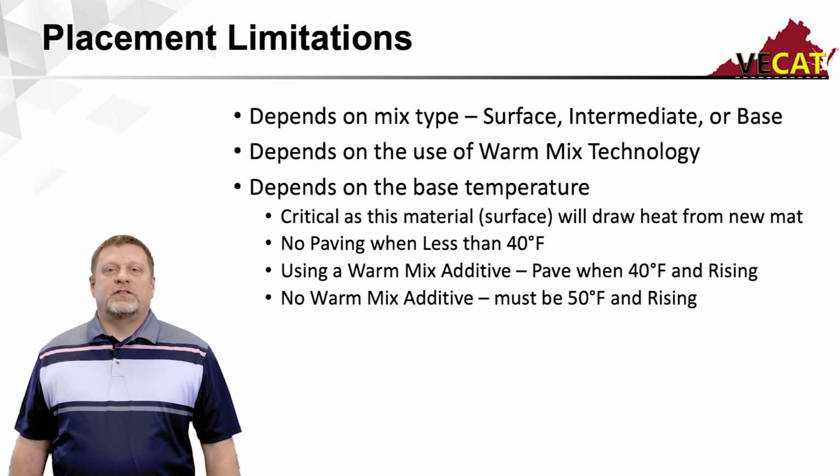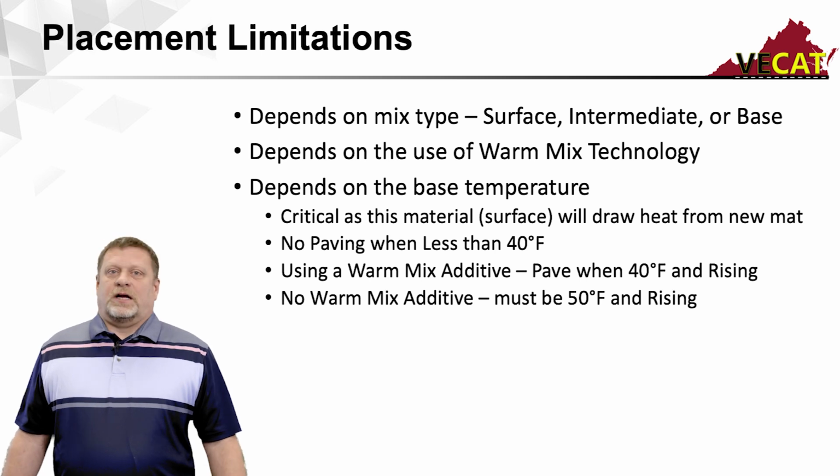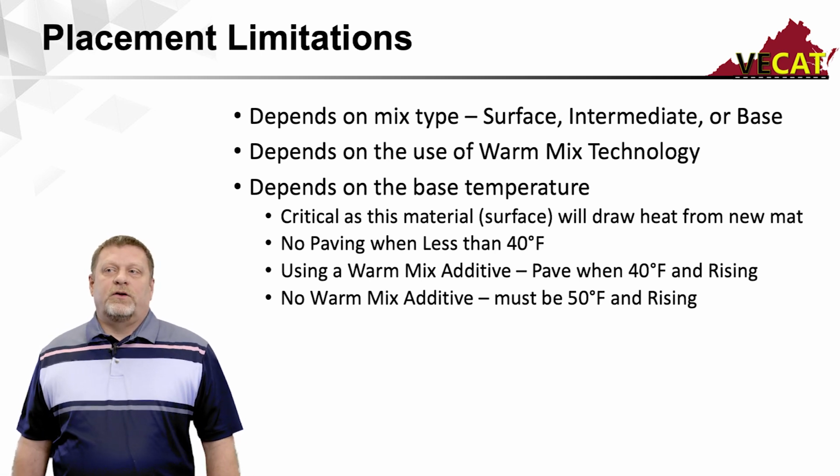So we would have to determine that the temperature is actually increasing a little bit, even though it's down near 40. But if I don't have a warm mix additive, that's our typical hot mix. If I'm not using a warm mix additive, then it has to be 50 degrees Fahrenheit and rising before I can place any mix.